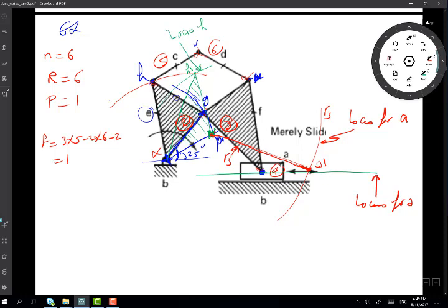So now I have A prime and I have G prime. Both A and G represent one side of this link 3 triangle or lamina, and because I know the lengths of the other sides, I can simply use two circles intersecting to find the new position of U, which will be U prime.